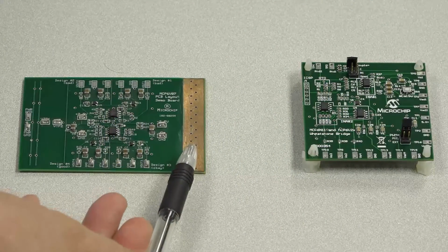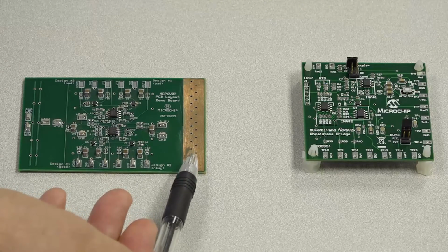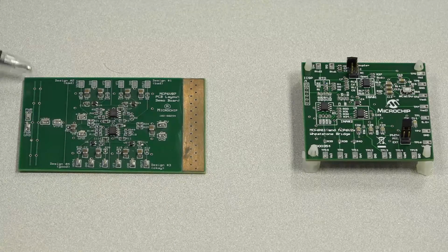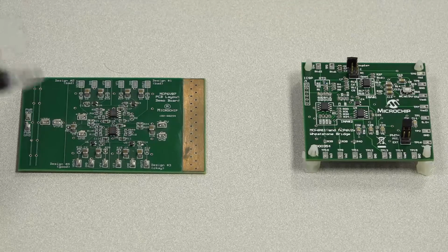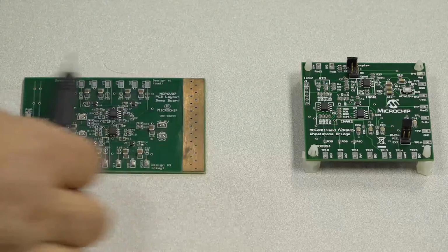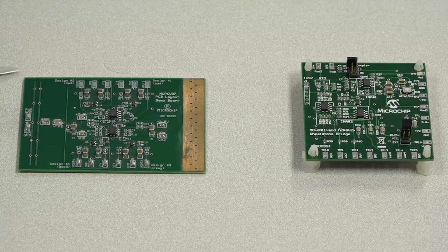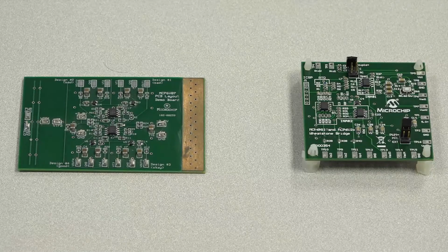On this end, you see the bare copper. I put that in an anvil, a large steel anvil, as my thermal ground. And then I have a series of resistors on the back of the board here on this end, equidistant, and I put a lab supply putting a lot of power in there. I forget the number now. I think it was on the order of 5 watts, something like that. And so it heats up this end of the board and you get a line source of temperature. And so you get a constant gradient going this direction and very little change this direction. And then I have 2 dual op-amps here in the center with circuits built around them. So let's go back to the screen.